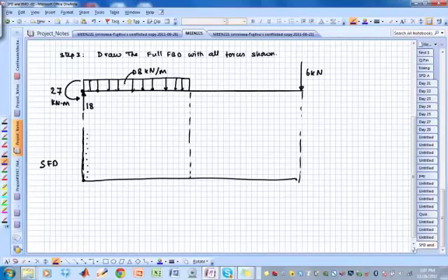I'm going to draw that in blue. So you can see I went up 9. That's this guy. Then this says go down by 8 kilonewton for every meter. This is a downward slope. Remember, the slope of this figure is that figure. So we are going to go by a downward slope. How far should I go? The area of this thing will tell me. Notice that I have to go down.